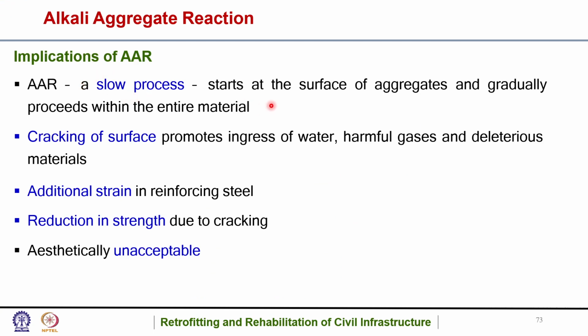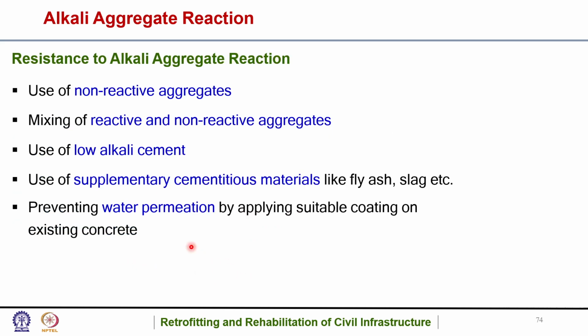So it is a slow process. It starts at the surface of aggregates and gradually proceeds within the entire material. Cracking of surface promotes ingress of water, harmful gases and deleterious materials. Additional strain in reinforcing steel, reduction in strength due to cracking, aesthetically unacceptable.